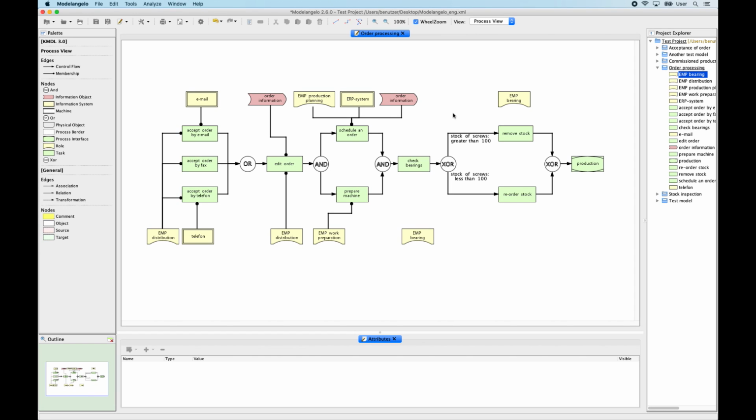To connect your defined role with a task, you need to insert a so-called membership line between the shapes. To do this, use the membership function in the top left menu bar at Edges. Before you begin, click on an empty area to make sure nothing is highlighted. Then select the membership line with the first click, next the role with the second click, and then the task with the third click. Hereby, take care to click in the middle of the shapes. To adjust the membership position, click on the line, and while holding down the mouse button, move the position.